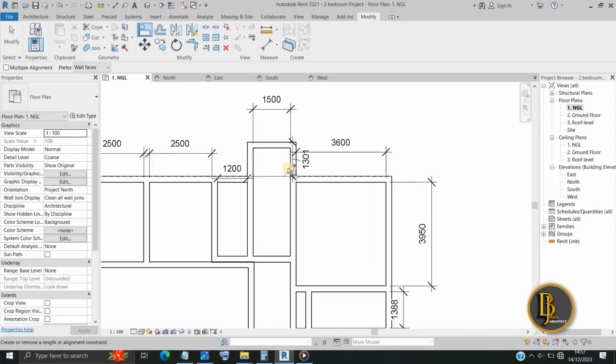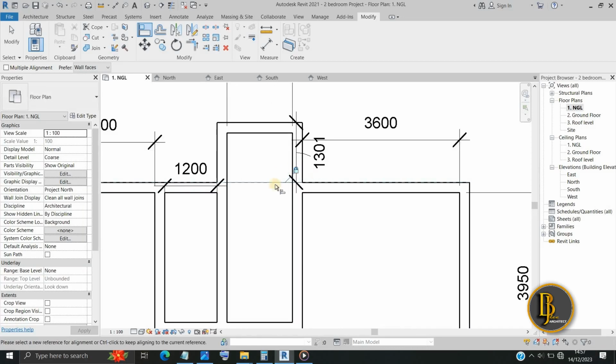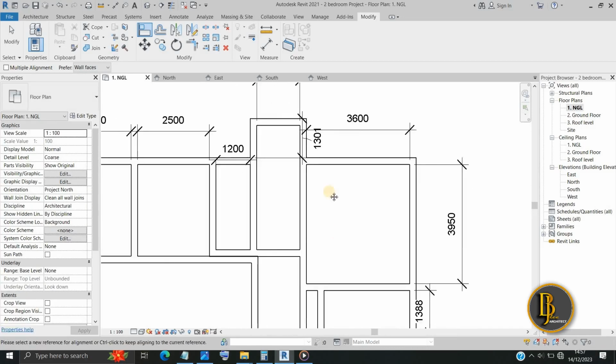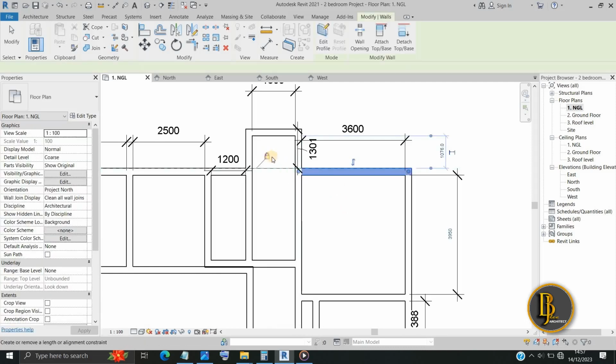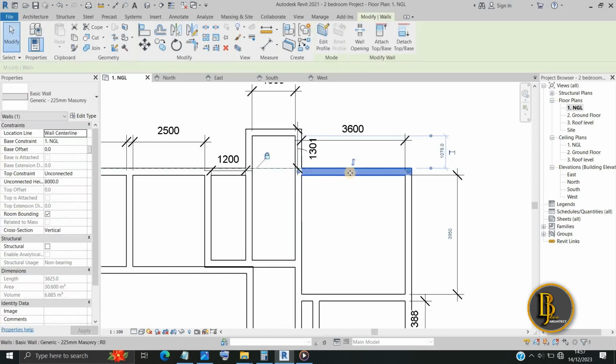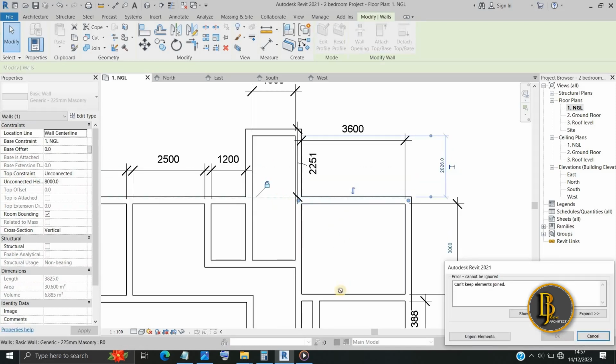You can also lock proportion so that when you shift it, it would. Let me show you something. Just for reference, the reason why I locked proportion, this padlock you see here, is so that if, for example, I move this wall, everything would move. I see all the walls have moved. That's why you lock proportion.